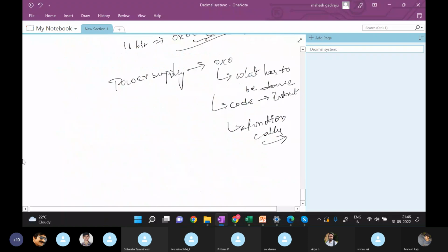Yesterday we were discussing, right? The controller might be having nearly 30 to 140 pins. So we cannot give 1, 2, 3, 4 until 140, right? So that's the reason they will be segregating. If it is having 150 pins, then they can segregate it into 5 ports, P0, P1, P2, P3, P4, something.